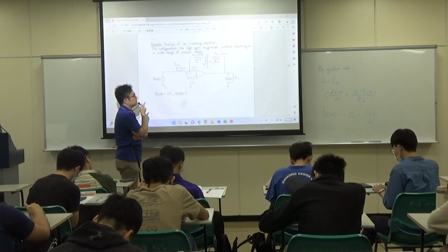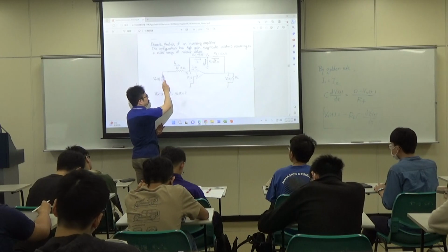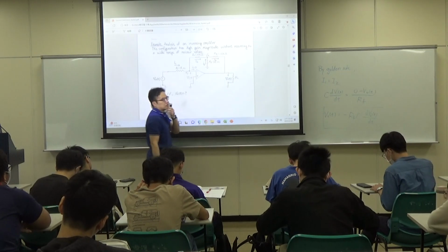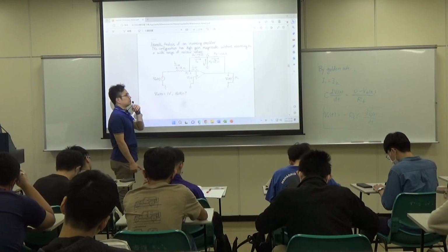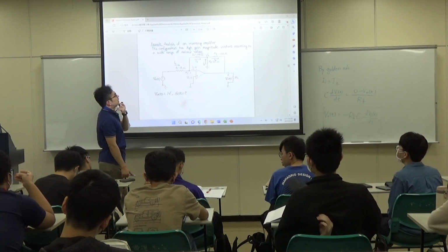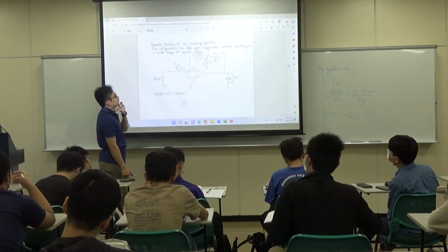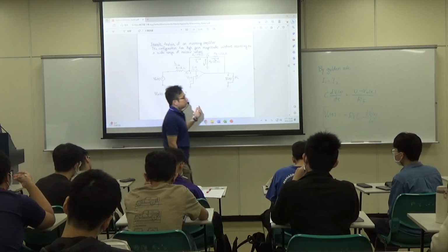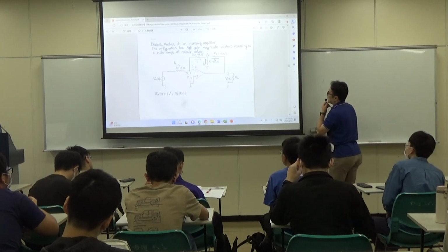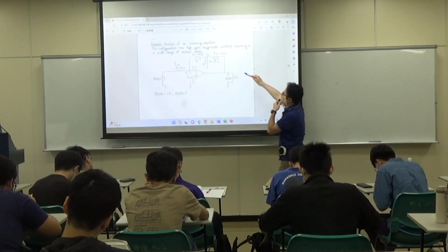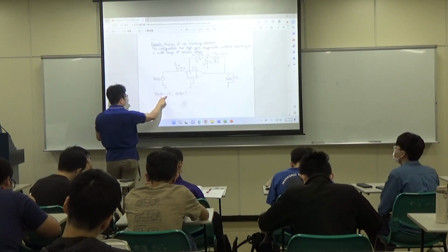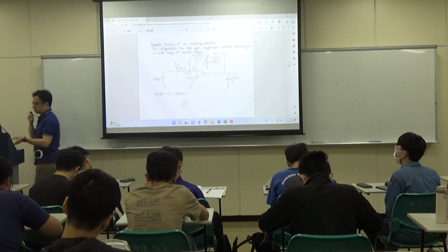So what happens? Because the input voltage connects to the inverting terminal, we know the output will be minus a value times the input voltage, since it's on the inverting side, and the positive terminal just connects to ground. This configuration has high gain magnitude without resorting to a wide range of resistor values. What does that mean? Let's solve for the relationship, given the resistance values. How about we calculate VO first? If the input voltage is 1 volt, what's the value of the output voltage?